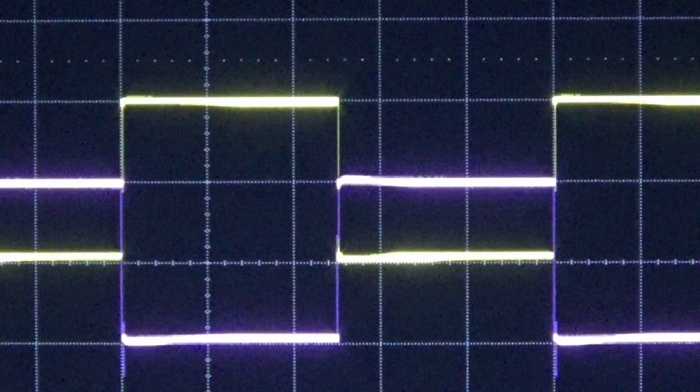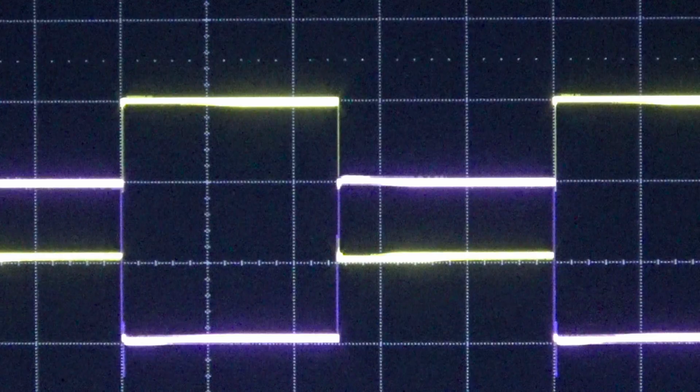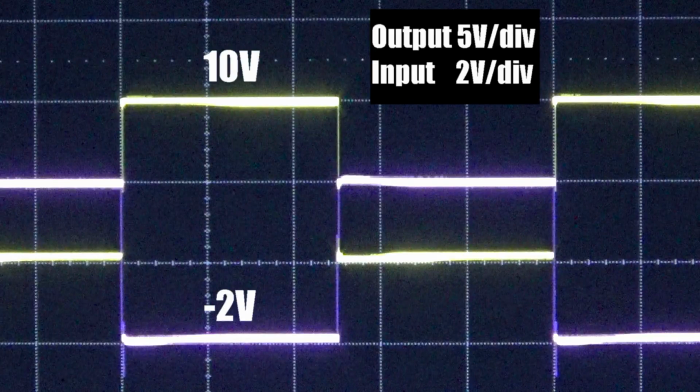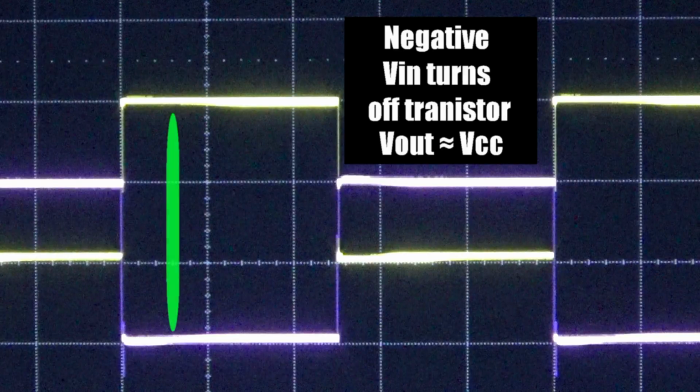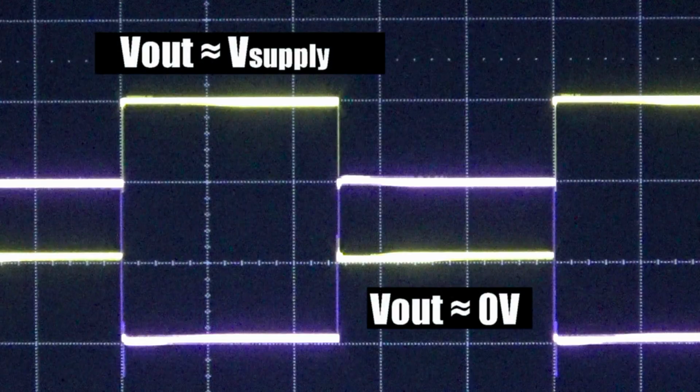Here's a look at the input and output when there's no capacitor connected to the output. The input signal is a plus and minus 2 volt peak-to-peak square wave. Notice that when the output is high, the input is negative. This is when the transistor is off. The output voltage is approximately equal to the collector-emitter junction voltage across the transistor, and it's approximately equal to the supply voltage. When the input signal is turned on or high, the transistor turns on, and the output voltage is approximately equal to zero. The output voltage follows the collector-emitter junction voltage.